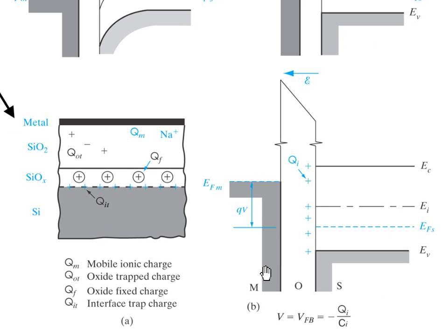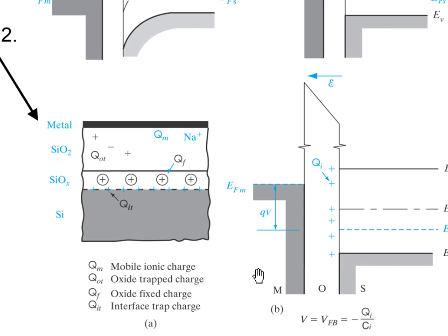If your water is not absolutely clean, if you're not using DI water, the charges in the water can actually get into the semiconductor. And that will mess up your semiconductor big time. So if you have positive charges in the gate, these are called trap charges. Whenever you have charge, it alters the electric field, right? Charge determines electric field determines electrostatic potential.